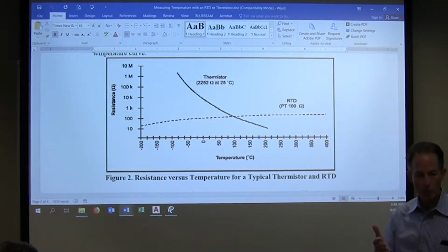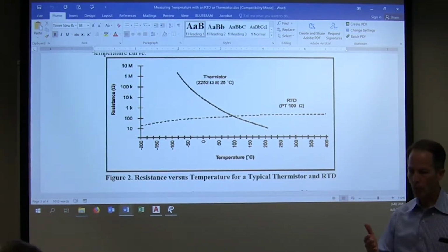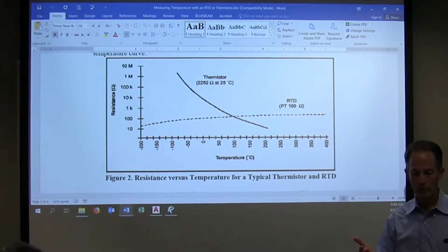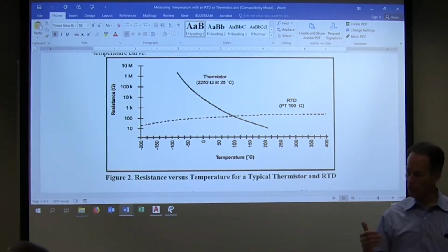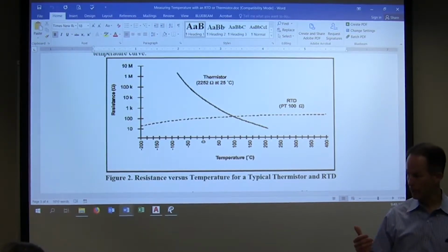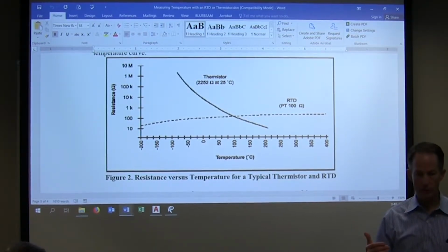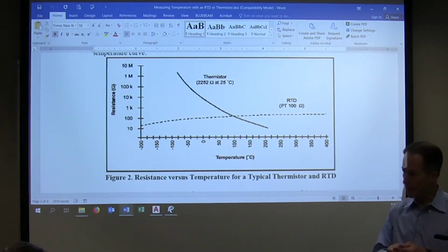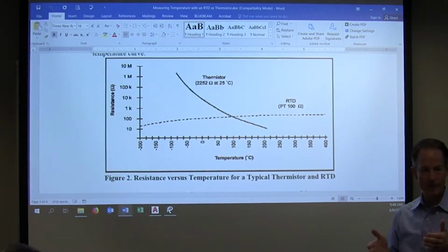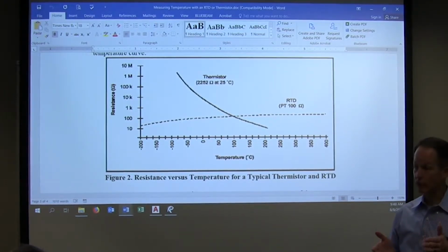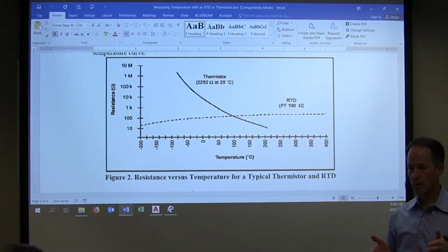All right, now let's look at room temp. What would we be at, 72 or 70? We'll say it's 11.8. Okay, so we're just a little bit above our 10,000 ohms, right? We're 11,000. So again, if I put my meter on a space temp and I'm somewhere between 11,000 and 10,000 ohms, that sensor's probably reading pretty good.